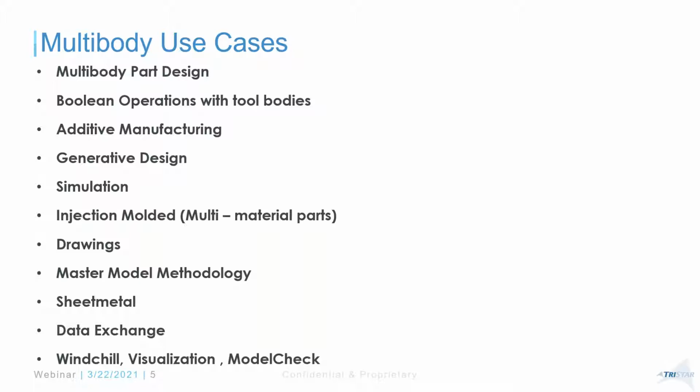You probably have different use cases depending on the industry you are in and the products you're developing or designing. So one thing is Boolean operations. You could use one body as a tool to subtract geometry from another body. Typically you would have used quilts and surfacing. You might be a surfacing expert where you did some quilt, merge, and then remove or solidify. So we have an alternate and easier option now, rather than having a giant model tree with a lot of curves and surfaces in there. You're probably able to do that with solid bodies now.